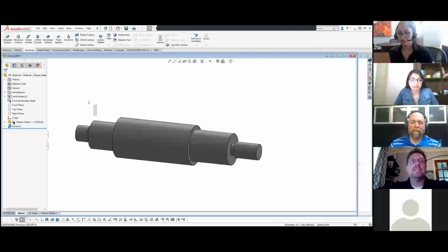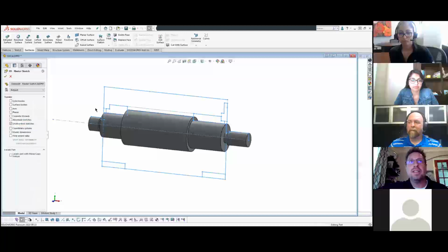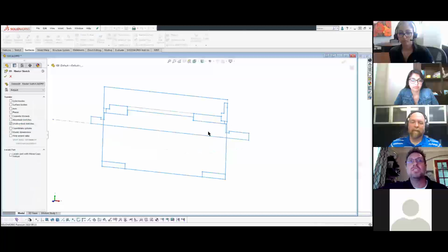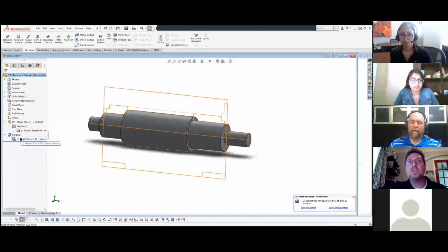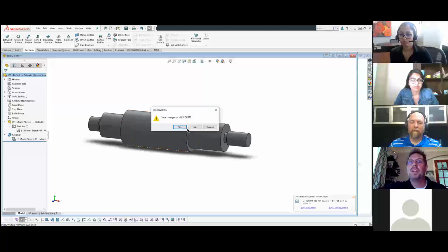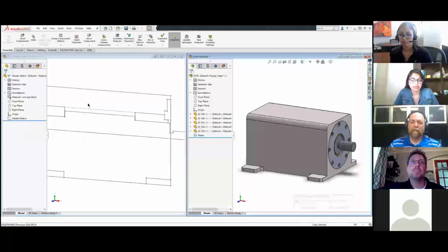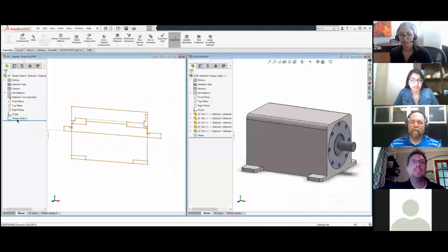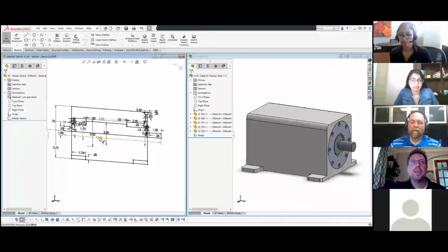All I've done is inserted a part into a part. And all I've done is just inserted that unabsorbed sketch. So I'm just using that same sketch over and over again through all of these individual parts. And then I'm using the contour select to just select on the inside of that to rotate around. And what this allows me to do is to change something that's fairly simple, like this master sketch. So I'll change 2 dimensions just to make it quick.